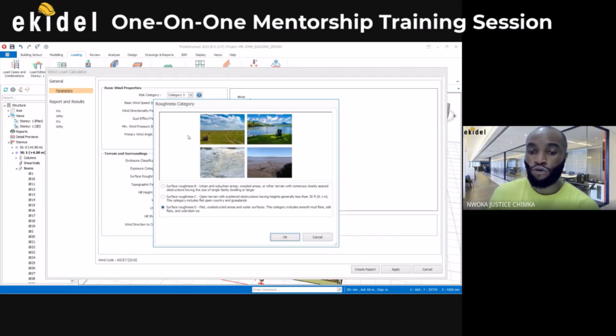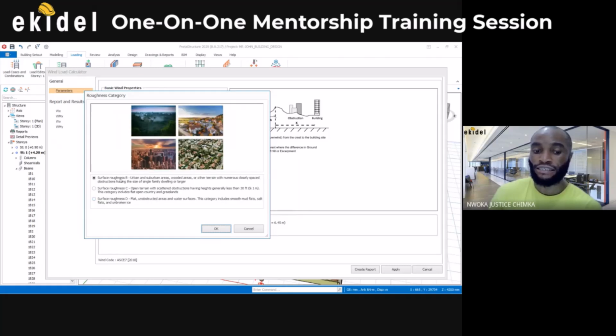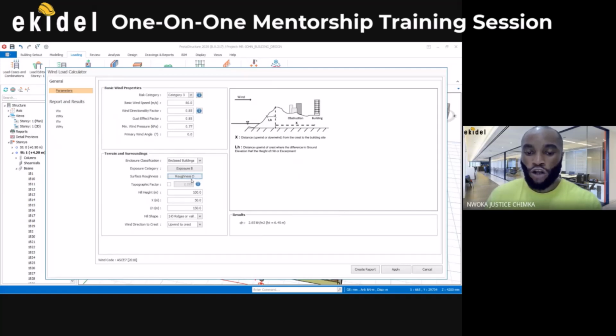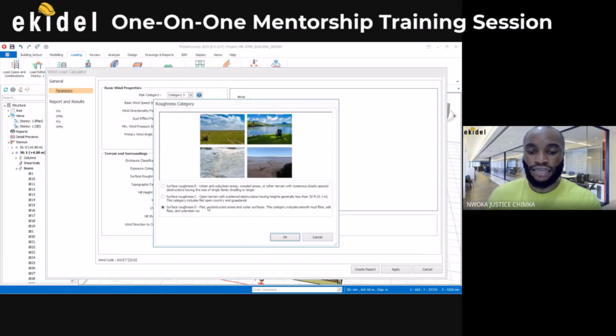So anything you choose here will also affect the wind pressure, because if it's in a flat land, there will be much wind attack on your structure. So let me assume again that this building is to be built in an urban area, that's in the city. So I'll come here and click on this. If I also choose a different thing, let me say category D, what you choose here will also affect what you choose on this exposure class B. Because you can't choose B that is in a city and then choose that the rough area is in a desert. So that's what it means.